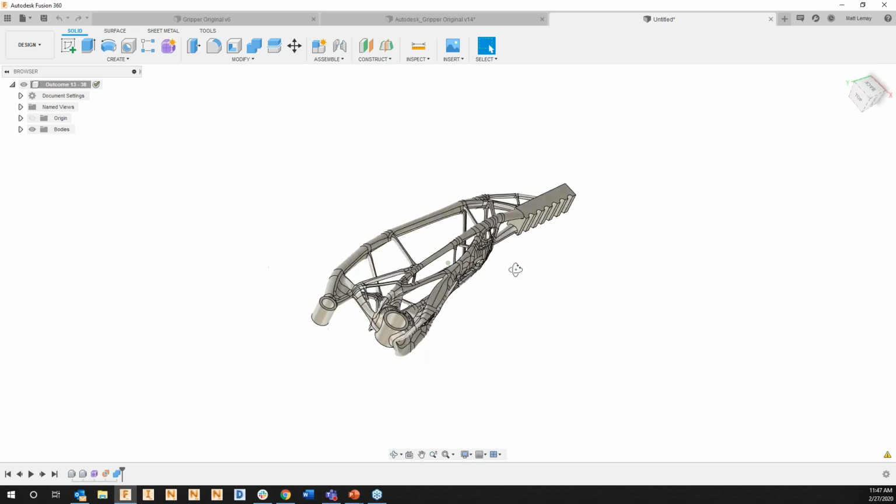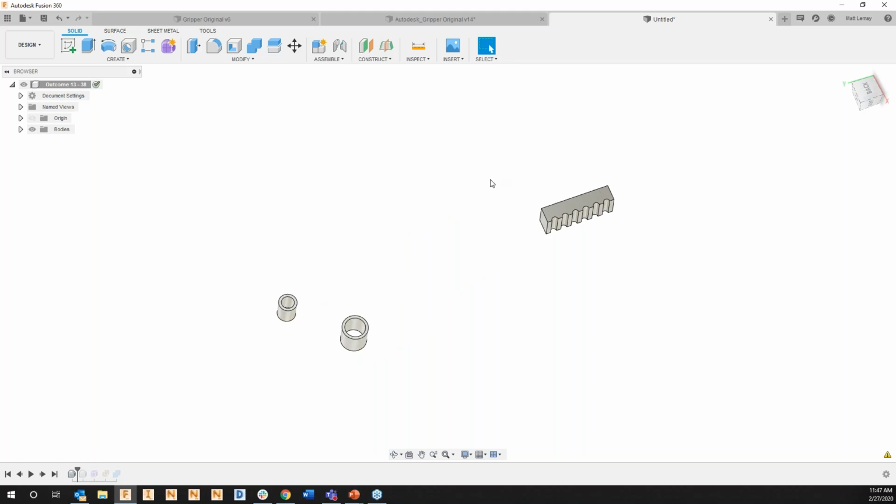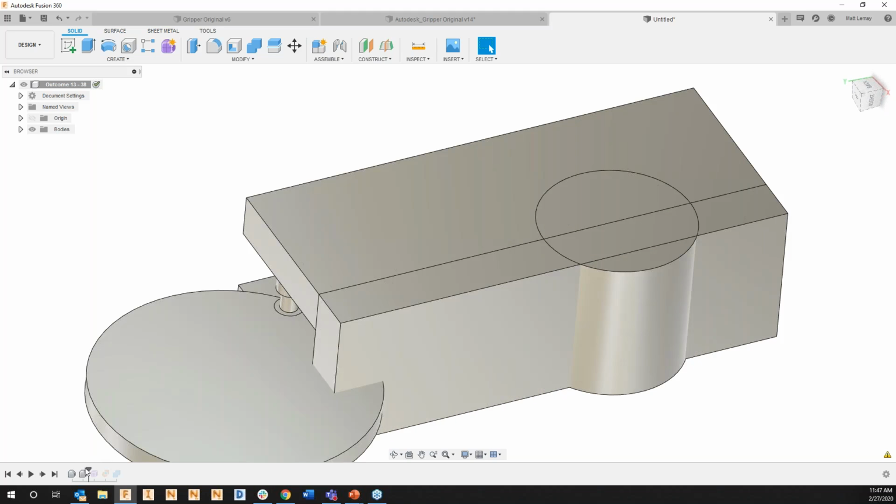So here you can see a new window appeared and we have that generative component. The first thing, just to really understand what Fusion is doing with these, is you'll see a timeline to the bottom left. And as we scale this back, you can see our preserves have been created here first. So these are, again, what we told Generative we need as the keep-in geometries themselves.